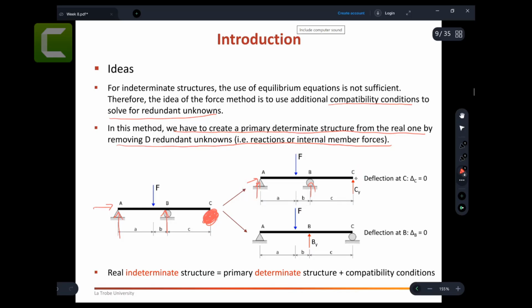But here we remove something, so there is an extra force that you just need to put as CY. We don't know. There is an additional force that is there, that is CY. Now, what is this force? When I remove these supports, before, this beam will have this kind of deflection. Do you agree with me? That is the deflection shape for this beam.